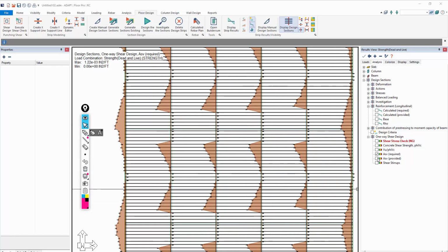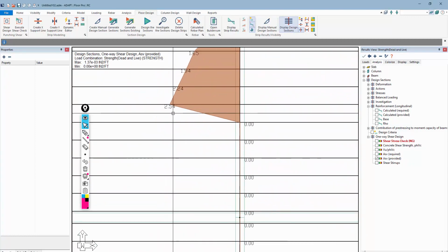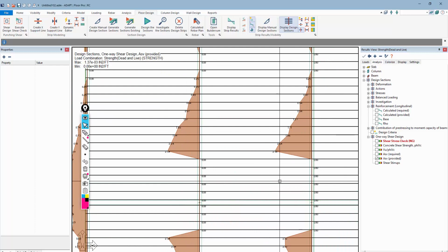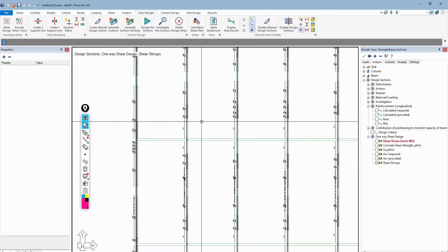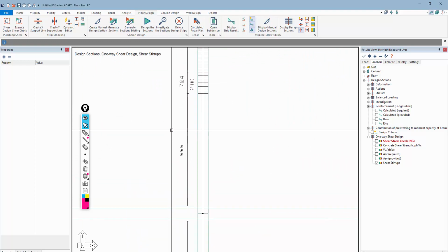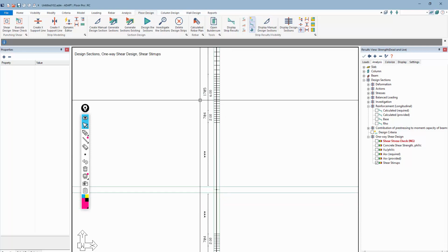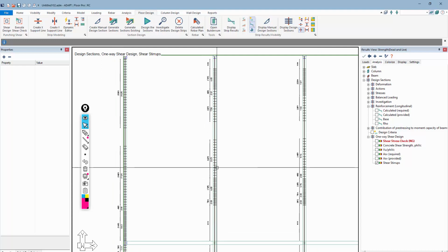The next thing is what's provided. This is the shear reinforcement provided. So you can see, for example, we needed 2.52. The provided reinforcement is actually 2.54, and that's just a function of the area of steel based on the size of reinforcement we're using. And then finally, we can look at shear stirrups. The program will show us on each of the beams, it just flattens this, it shows us the reinforcement layout. Again, from this point out to here, we have exceeds code, and then we get into that same kind of layout view that we saw in elevation earlier.